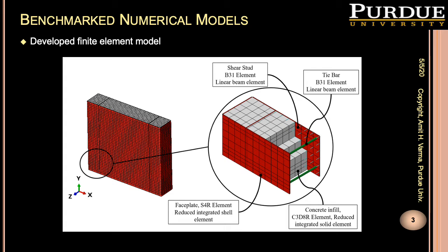The stress analysis was a two-step process. In the first step, an incremental axial compressive load was applied to the model. The magnitude of the load was increased from 0 to the maximum value in an hour. And in the second step, the axial load was maintained constant while the nodal temperatures obtained from the heat transfer analysis were applied to the model.